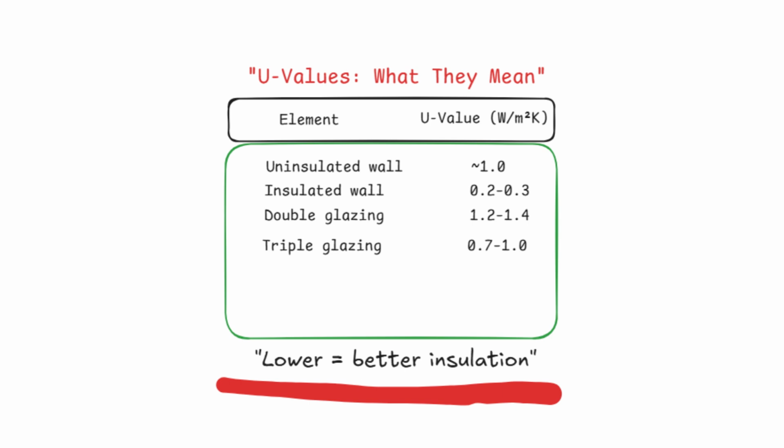You don't need to do the full calculation before your installer visit. You need a number good enough to have an informed conversation. Here's the rule. Multiply your floor area in square meters by a watts per square meter figure based on your house condition. A well-insulated modern house, 40 to 60 watts per square meter. An average house with mixed insulation, 60 to 80. A poorly insulated older house, 80 to 120 or higher.